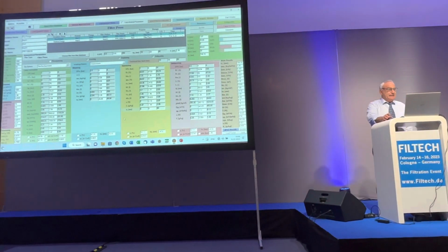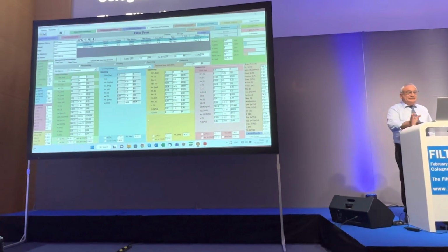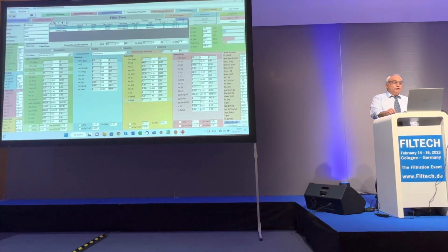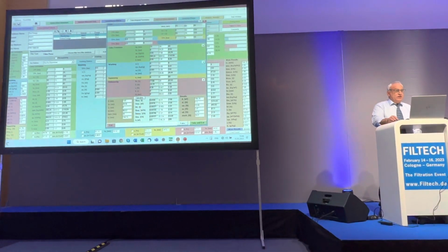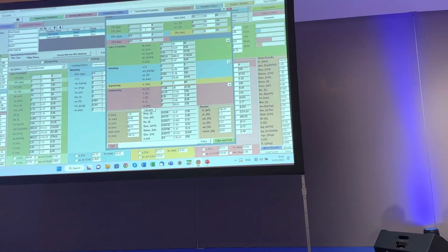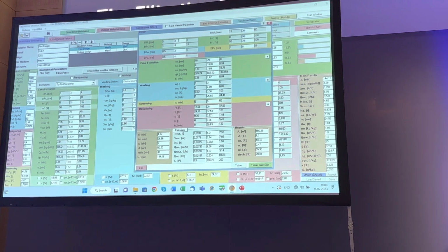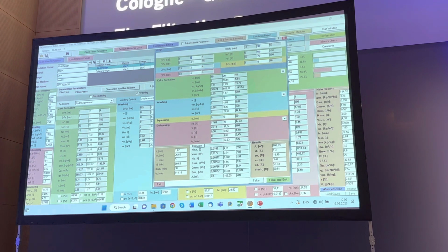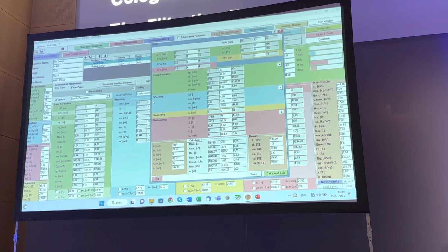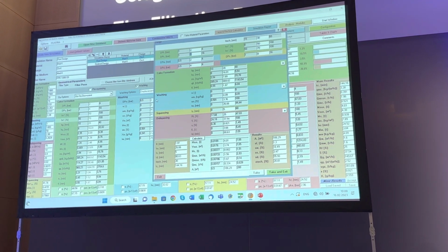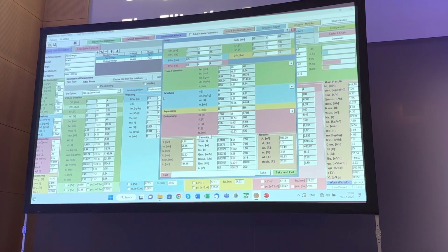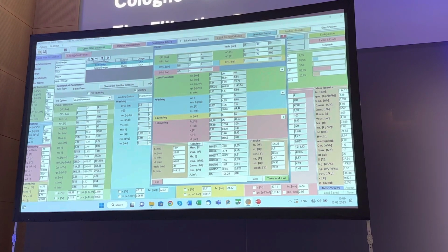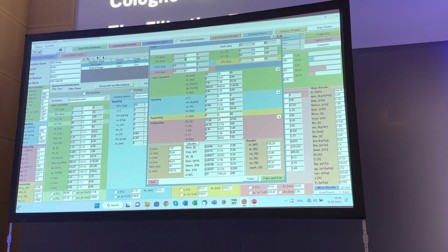And you see here, what we have is a definite design. We have a membrane filter press that is 2 bar maximal pressure with a centrifugal pump, and we want to do a rest filtration by using the membrane pressure. We do this in some cases, yeah? Not necessary, but we can do this. And then we wash with 2 bar.